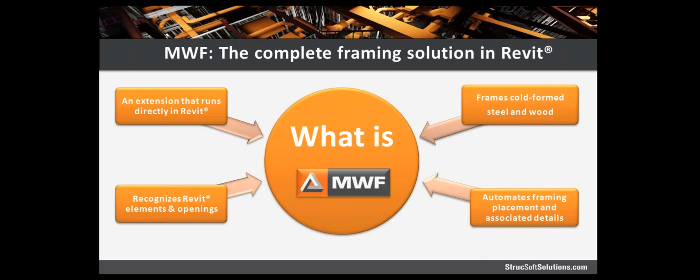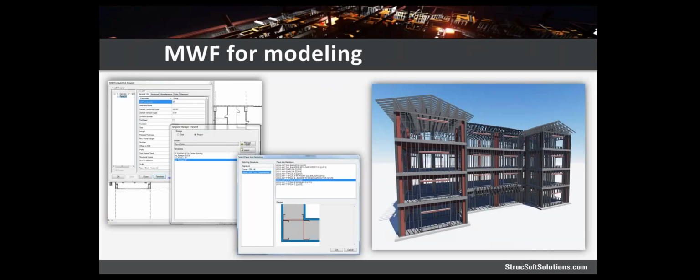So what is MWF? Well, it is an extension that runs directly in Revit and recognizes Revit elements as well as their openings. It frames in cold form steel and wood and automates the framing placement in Revit. The most important element of MWF to remember is that it is template driven. By assigning templates to different wall types, you can apply global changes and manage RFIs much more quickly than manually changing individual elements. This is the power of MWF.